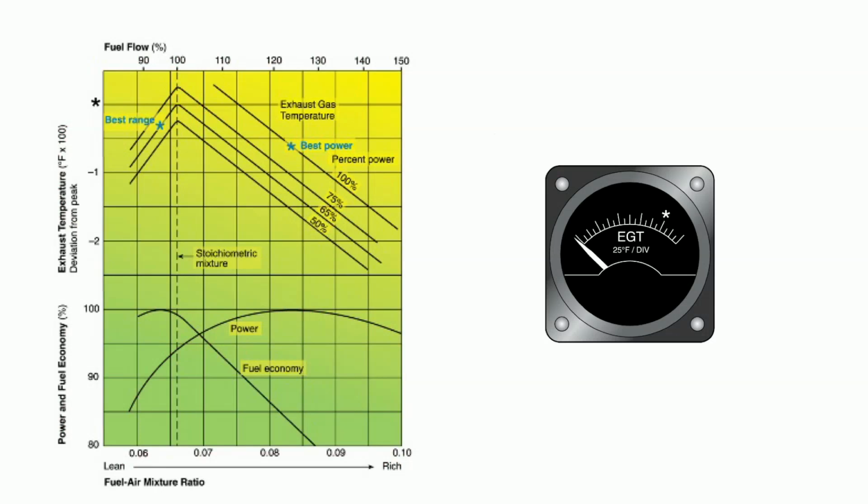And so along with those basics, we have a couple different things that we see. As mentioned before, we're going to have things like pumps that help to avoid things like vapor lock. We have strainers that are going to prevent contamination that could cause interruption through the fuel meter. We have the fuel metering device itself, and then we have some way of taking fuel from the fuel metering device to the cylinders, either through an intake system or through a direct injection method, which we'll talk about all of that a little bit later.